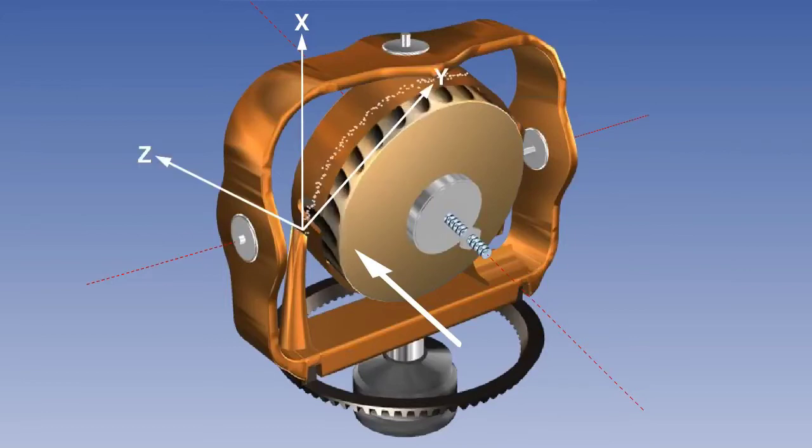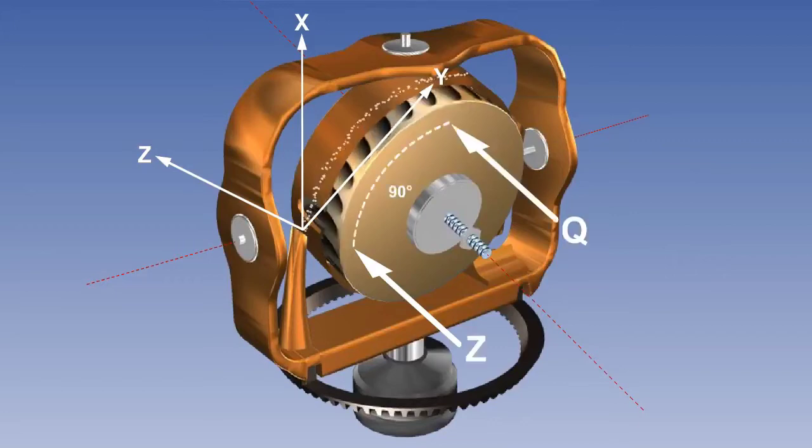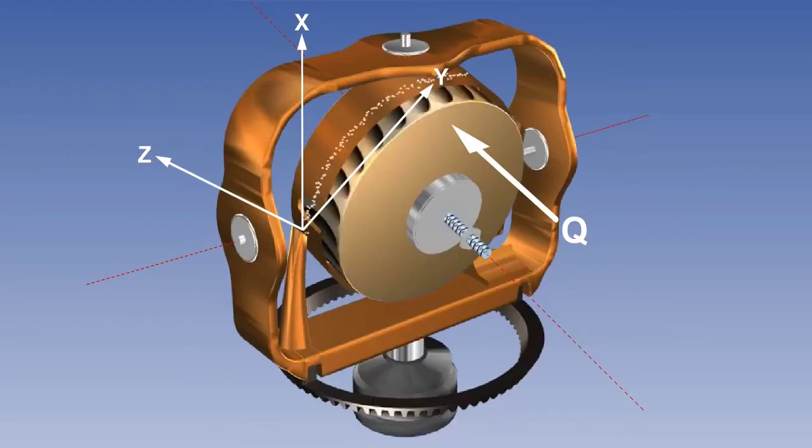As the air jet is fixed to the outer gimbal, the airstream now strikes the rotor at an angle. The resulting force can be resolved into 2 components, Y and Z. Component Z will precess the rotor as if the force had been applied at a point 90 degrees around the circumference of the rotor in the direction of spin at position Q. The effect is therefore to realign the rotor with its axis in the yawing plane.